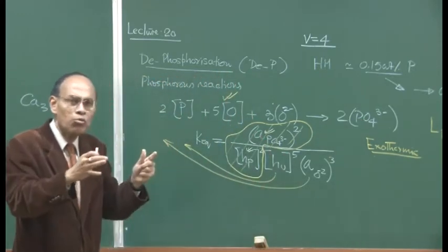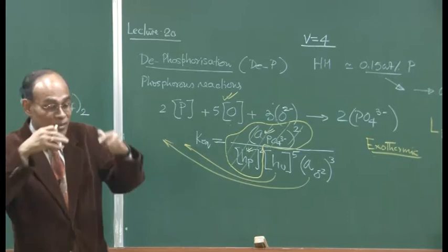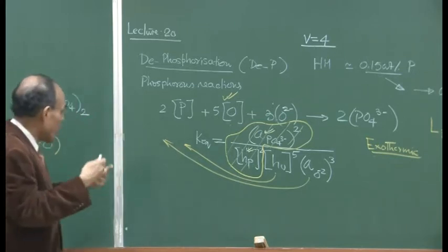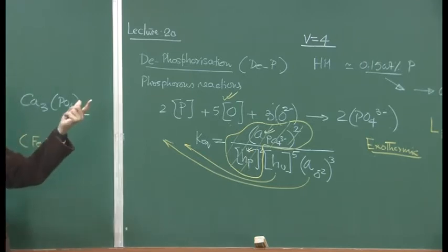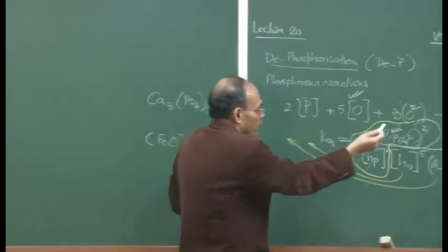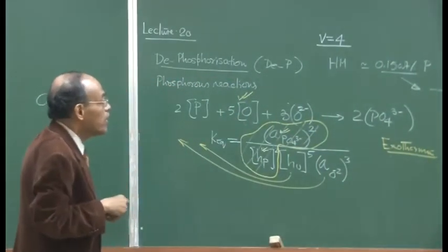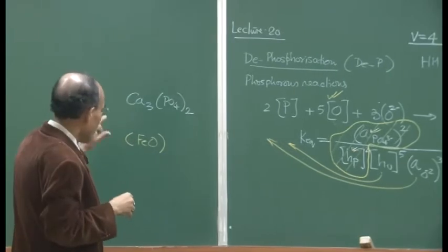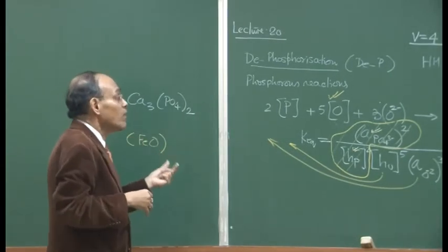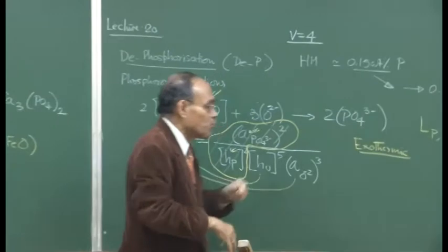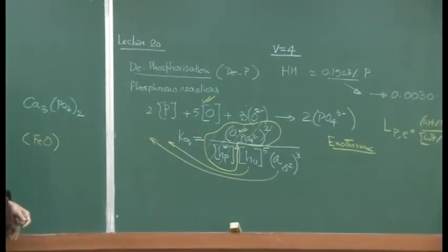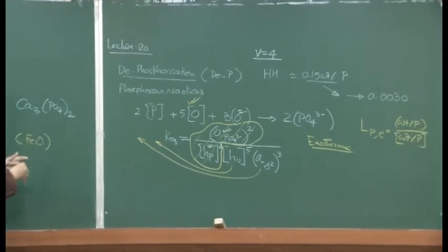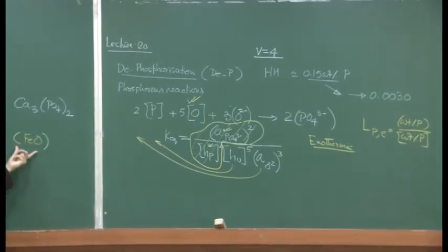In that case, despite having oxygen, a high oxygen potential, there is not a significant amount of phosphorus removal. So halfway through, the phosphorus removal is quite rapid, but come to the later point, or the end point of the blow, there is a chance, and if you play your cards wrong, you can land up with a huge temperature in the system, and as a result, phosphorus reversion. So we have to be careful towards the end of the blow, because our objective is to drive or eliminate phosphorus from steel. We do not want phosphorus to get back from slag to the metal, having successfully eliminated phosphorus. So temperature control, and that is why the endpoint control, is so important for us.